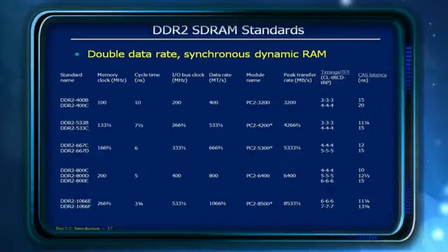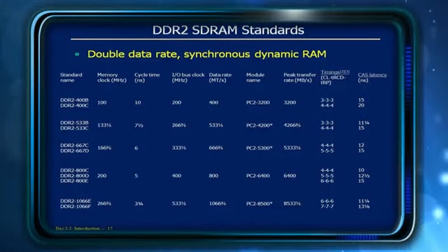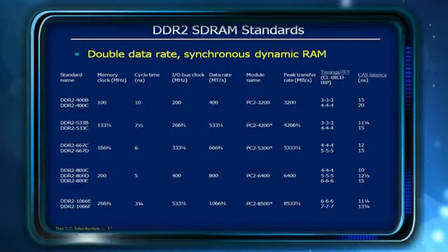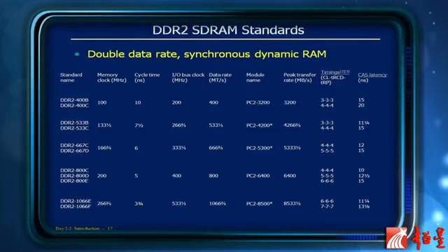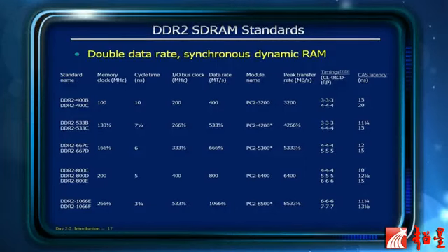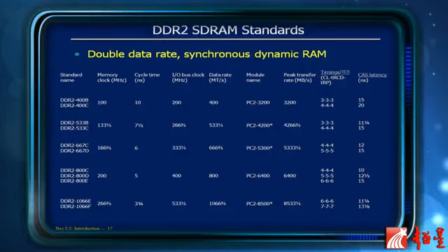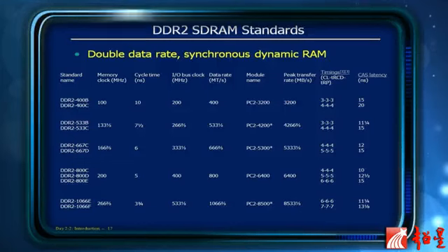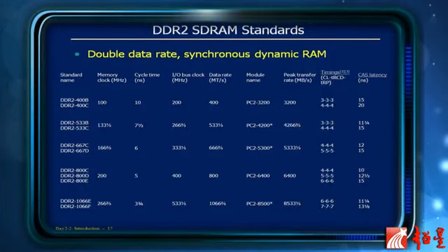This is DDR2. I just want to point out right now the clock speed of DDR2 SDRAM is about 260 megahertz. That's also pretty high. You can see the speed start from 100 megahertz, increasing to 260 megahertz. Of course, the transmission speed, because it's double edge triggered and so on, is in gigahertz. It's in gigabits per second now.